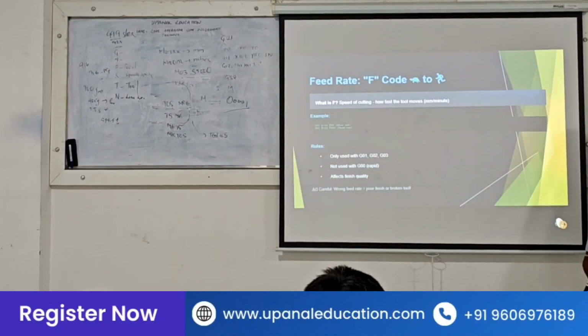Feed rate. Will we give feed rate with G00? No. Feed rate has to be used only with G01, G02 and G03, because feed rate affects the cutting quality, the line.